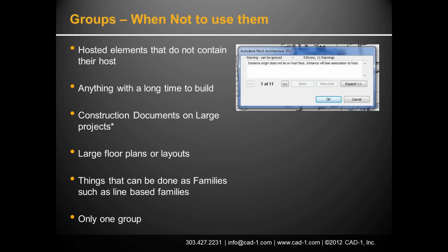Then you'd grab your table and do a bunch of other lines and make that a bed, and then group the bed group with the table group together and call that bedroom arrangement 1. Well, that was great in AutoCAD. Revit, no, that's not what we want to do. That's not how this is intended. When we're doing groups of that nature, you're going to want to build families and stuff.